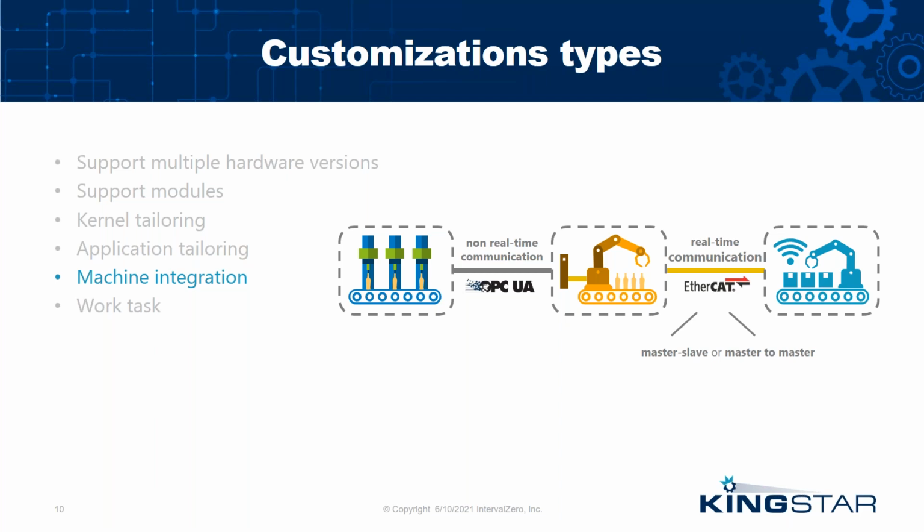Later on, there are standard protocols now being developed with OPC UA, TSN, and EtherCAT that allow smooth integration. But there are many older machines already in the factory. Nobody will replace the whole machines at the same time. And there are possibly, or most likely, already automation protocols used in the machine for communication with SCADA and with other machines. For this reason, the machine builder must allow adding extra protocols on the machines or adding extra IOs for this kind of communication.